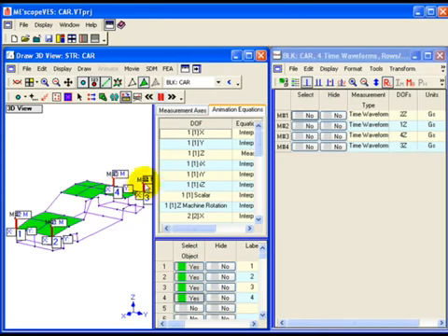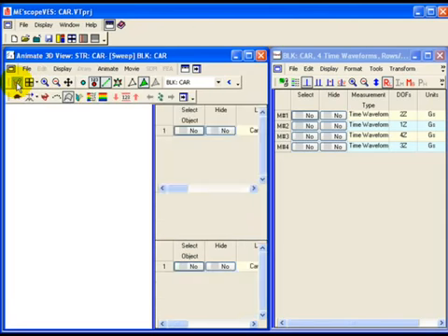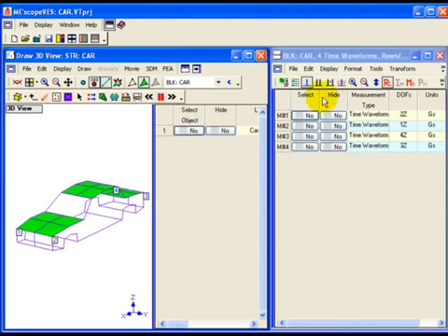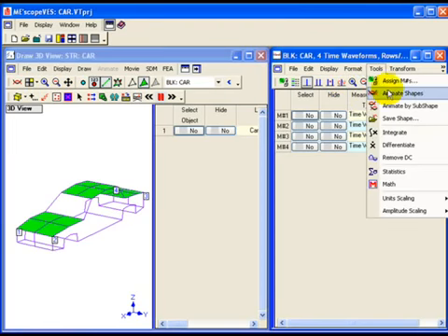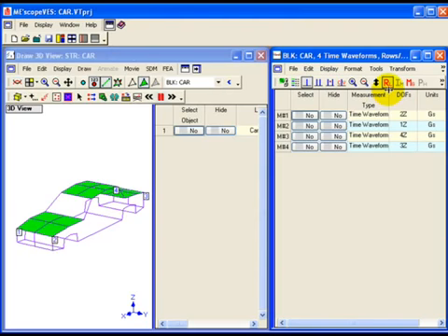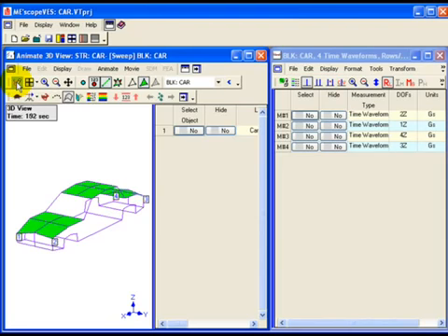There are 2 ways to initiate animation. Execute Draw, Animate in the Structure window, or execute Tools, Animate Shapes in the current animation source window. When animation is initiated, only the points and directions with measured equations will move, unless the Animate interpolation command has been executed. Execute Draw, Animate in the Structure window to initiate sweep animation again using the newly created measured animation equations.